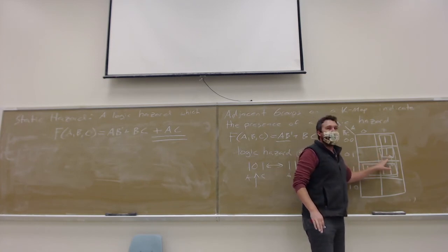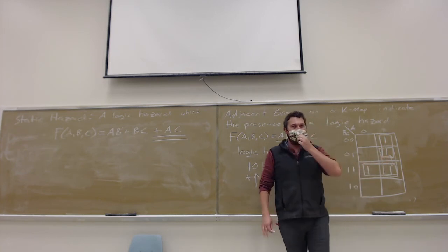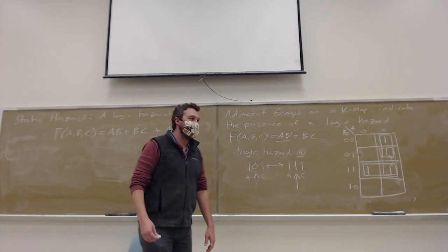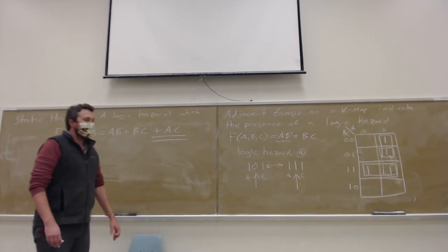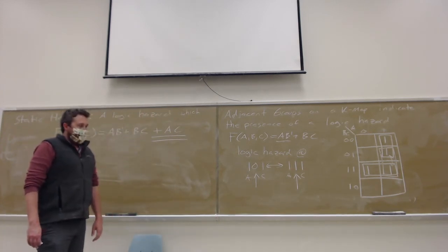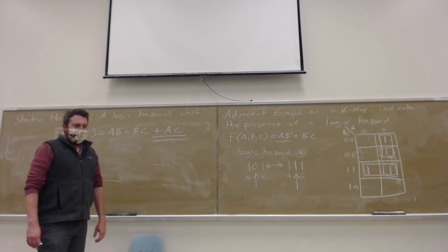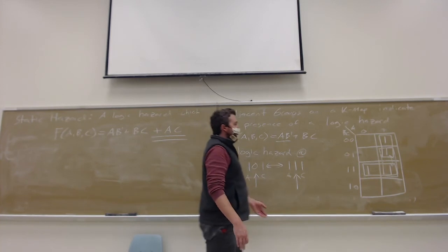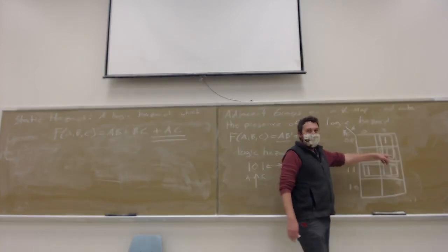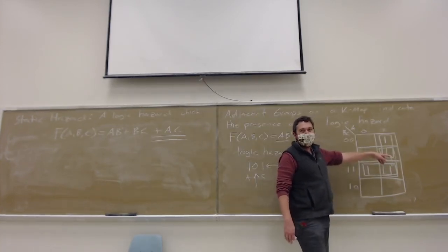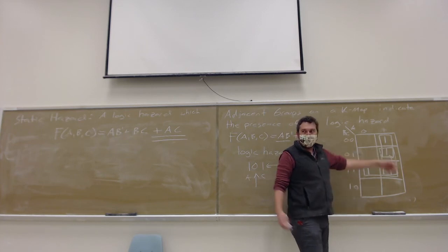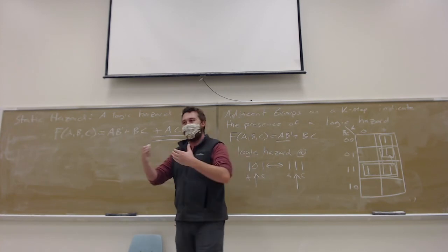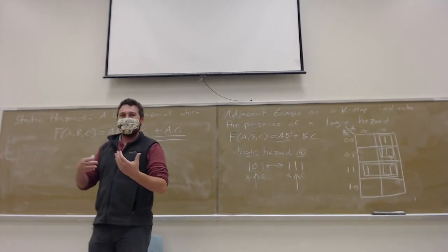But the conversation is going to revolve around what will happen if that logic hazard occurs. If the answer is an extra clock cycle or something to get the calculation that you want, or something simple happens, it's not a big deal, right? But if this logic hazard means the missile will explode while it's still attached to the airplane, then you want to add the consensus term, right? Then you're weighing risk versus cost.